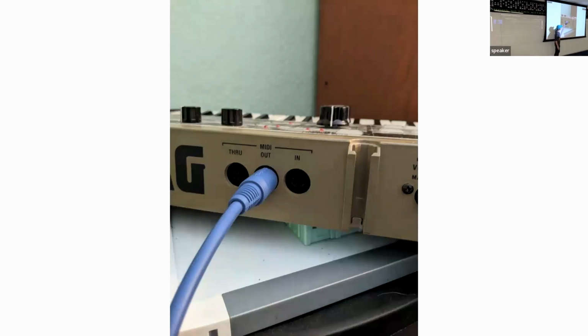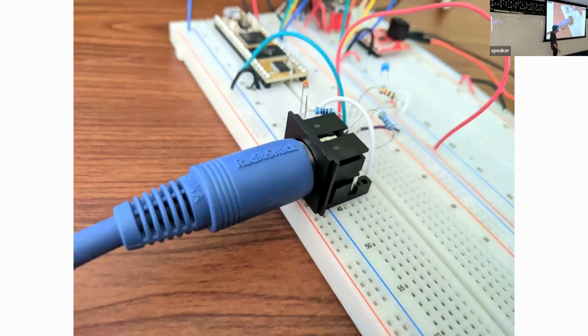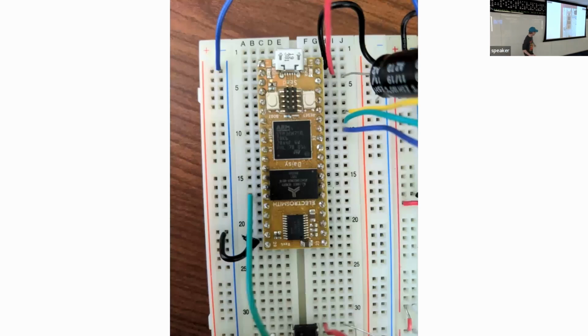We talked about the MIDI coming up here, the digital UART data output by the synthesizer here, coming through a 5-pin MIDI DIN connector, coming into this breadboard connector here, going into our MIDI input circuit, being converted to light, and then back from light to an electrical signal of ones and zeros that are being sent from this wire into pin 14 or 15, I can't remember, but going into our program through the UART driver, our program cranks on that MIDI data and